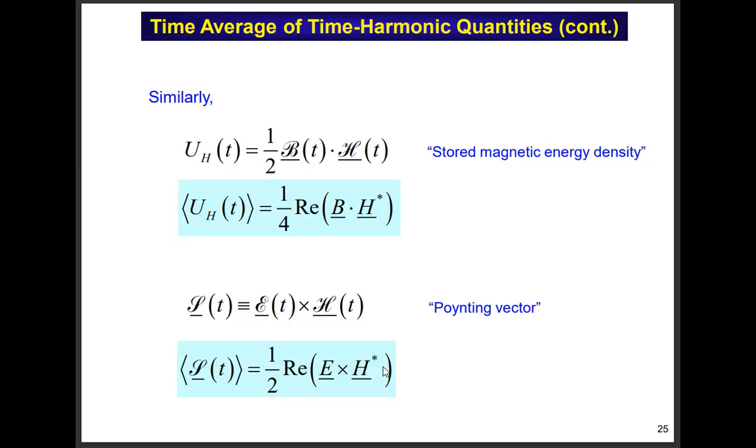Think of circuit theory. Complex power, 1/2 V I conjugate, the real part is watts, right? But now it's watts per square meter of a wave. So in circuit theory, I have 1/2 V I conjugate. The imaginary part was what again? VARs, the reactive power. So what do you think I'm going to get if I take the imaginary part of 1/2 E cross H conjugate? The VARs per square meter flowing in our wave. Right, exactly. Good. Okay, I'm just setting you up for notes 5 later. We're at the end.